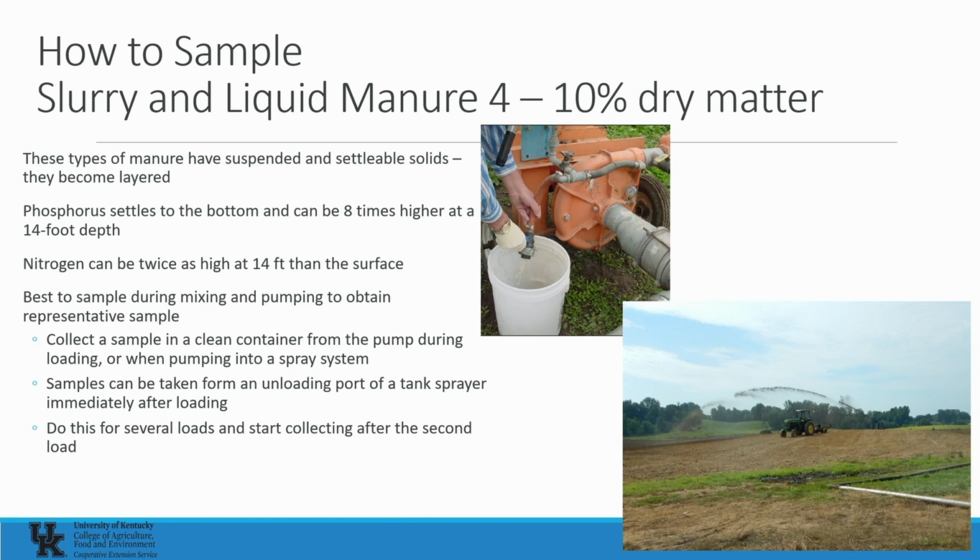We can take it from an unloading port in a tank spreader, but we want to do that before those solids start to settle in that tank spreader. And we want to do this for several loads and always start collecting after the second load. And the reason for that is that it allows for that lagoon to get mixed thoroughly.